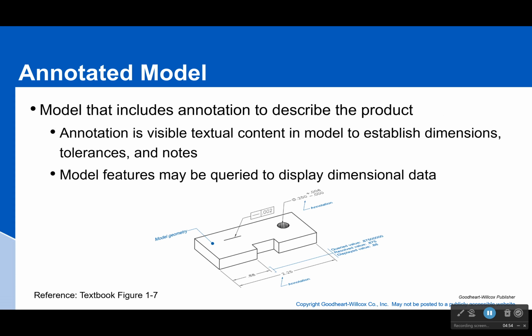It might also be because it gives you extra little details right here. For example, this 0.88 right here, that might be what's shown in the dimension. There's a lot of things that happen in SOLIDWORKS, it'll show that. But it might tell you, okay, well, if you actually measure things in your SOLIDWORKS model, it's not actually 0.88, it's 0.875.